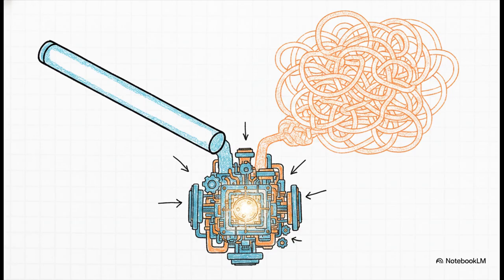But, of course, nothing is ever perfectly simple, right? While the Yule-Walker equations make the AR model neat and linear, finding the parameters for the moving average, or MA model, is mathematically way harder, because taking the expected value for MA models involves products of unknown filter coefficients. The whole problem becomes strictly nonlinear. You can't just solve a simple matrix. It requires complex, nonlinear optimization algorithms. But if you can solve that nonlinearity within the combined ARMA model, you unlock an incredibly powerful tool for synthesizing almost any random signal imaginable.